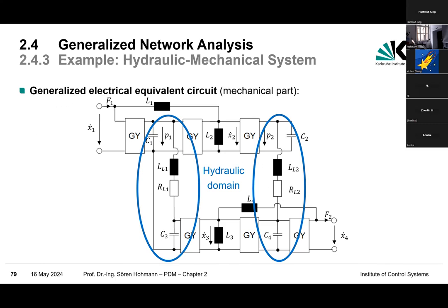The inductor and something else? If we put everything in derivative form, who brings dynamics into the system? Capacitor, right. So capacitor and inductor. These two are responsible for our dynamics. So for x dots, responsible are our storages.